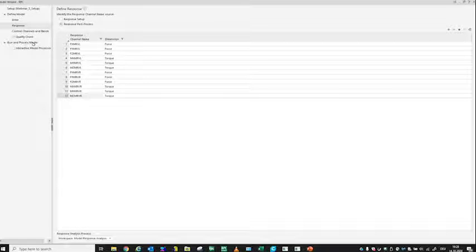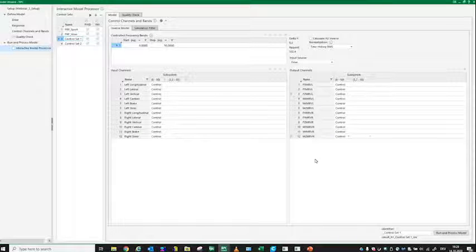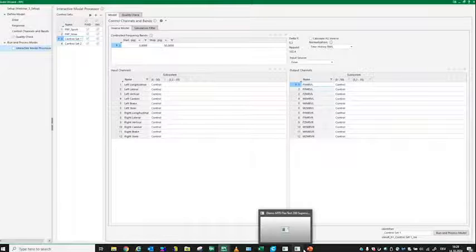Sorry for that. So now I removed the channels, and in the interactive model processor, or just in the inverse itself, I will get only the channels I'm interested in. So these channels I can now use to have then no control and control, and directly use them. So only for these channels later on in the simulate wizard, I will set the gains, whereas in RPC Pro, I needed to set gains everywhere. Okay, it is as easy as shown.